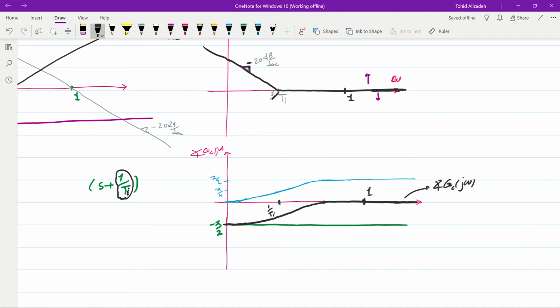And we just change the behavior of the system at the very low frequency. And you should keep in mind that we had a similar case when we were doing it using the root locus approach. We were placing a 0 pretty close to the pole at the origin in order to keep the root locus plot or sketch of the system the same. In that case, the transient behavior would remain the same.